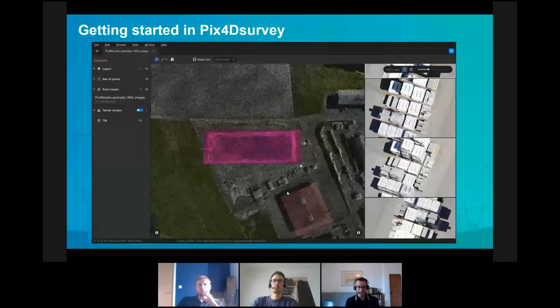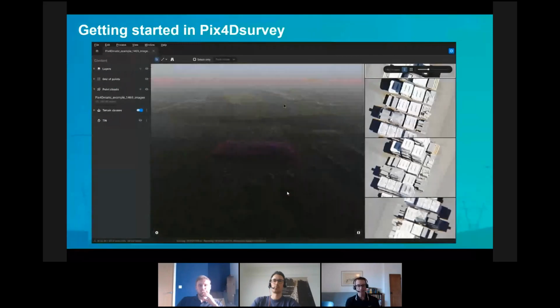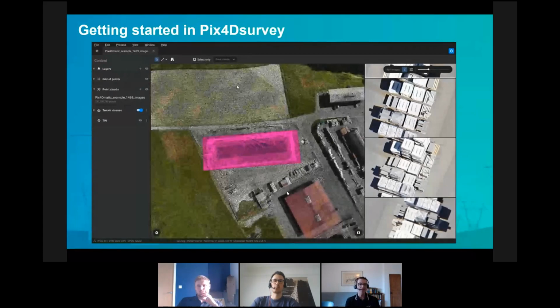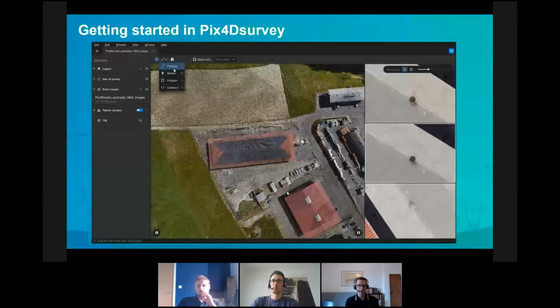But as you can see here, here's that selecting inside the point cloud. You can use that to reassign between classes, and you can even trim down what you're selecting. Like if you really want to select just part of a line, you can pick it here and just select some vertices, remove those. It's pretty flexible and useful. There's a nice set of manual vectorization tools. We won't go through that in too much detail, but I think you get the idea from what you see there of being able to mark things.